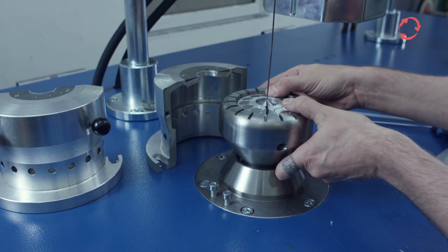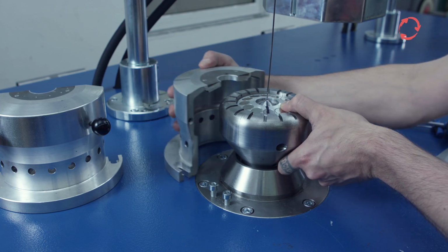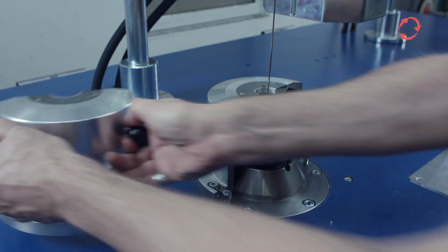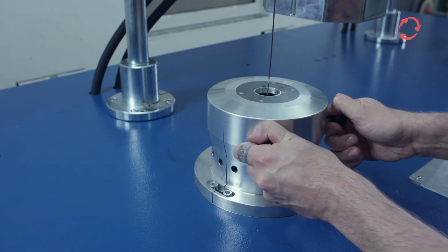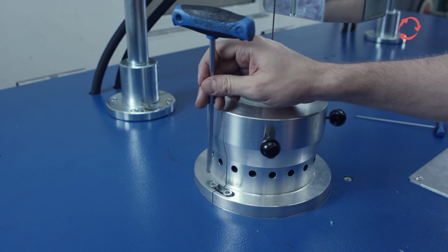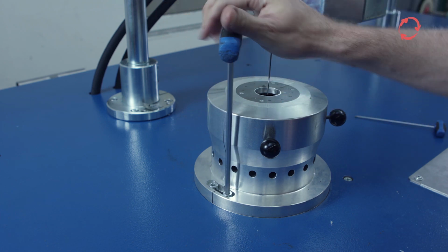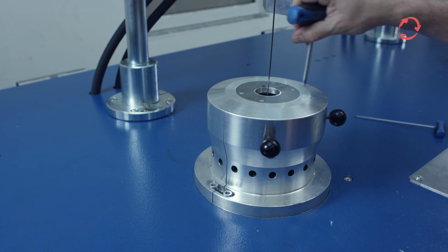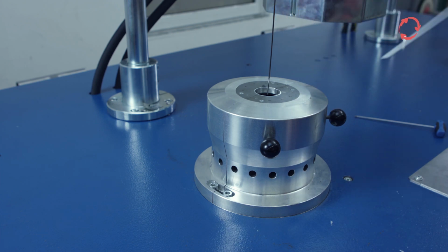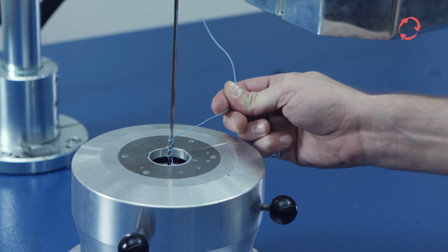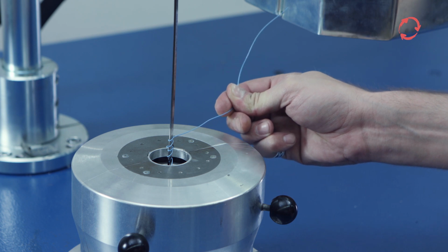The two covers of the winding head can now be remounted. It should be noted that the alignment of the marking for the mandrel is the same as the position for disassembly. Make sure that the screws are tightened. If the mandrel is twisted, it will be in the wrong position when closing the heater, which will prevent it from closing correctly. Now check the correct adjustment of the intake via a test run.